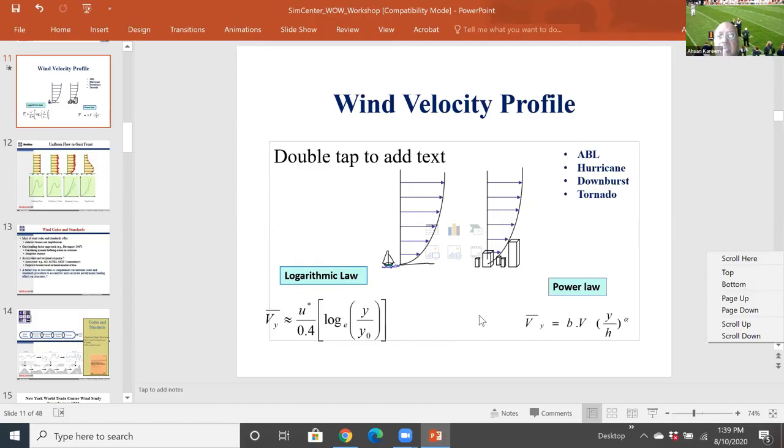Yes, because if you are just looking at very tall buildings like the one you are seeing in New York City now, or for bridges, this is cables. This is highly desirable to have this capability. But I think this area of a little cladding piece getting pulled out, then it will sort of flutter around the building. That is a local fluid structure interaction problem, which is essential also because that is the one which would enhance the stresses in the components and eventually the peel off. So hopefully that response satisfies that question.